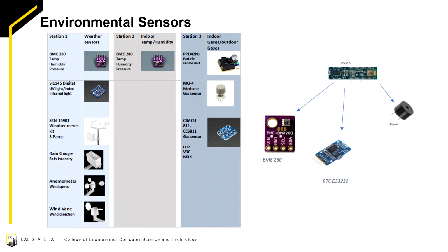Here is an overview of our sensors in their corresponding stations. Station 1, we have chosen sensors for outdoor weather applications and being able to send the data using the LoRa communication protocol to the central station. This leads us to selecting sensor BME280. This sensor measures three weather features, the barometric pressure, humidity, and temperature, with great accuracy.